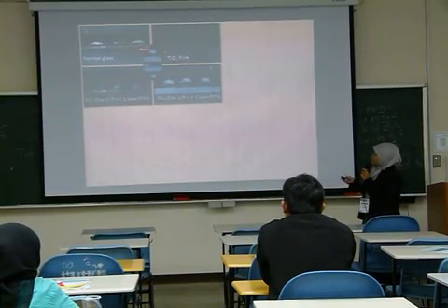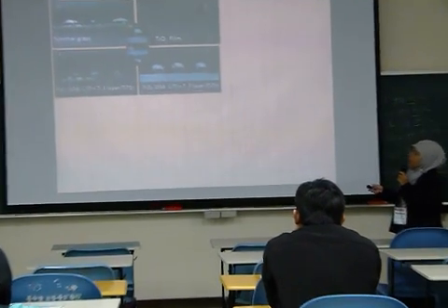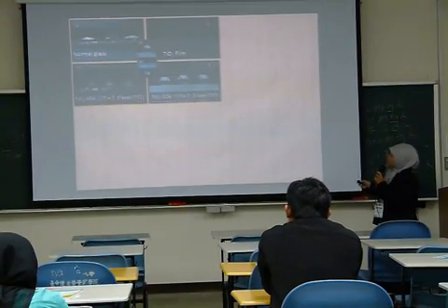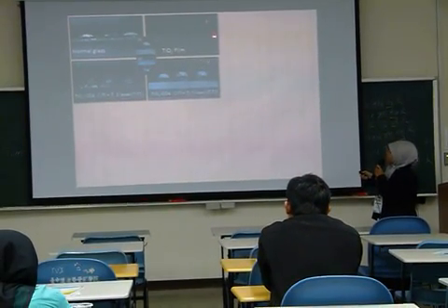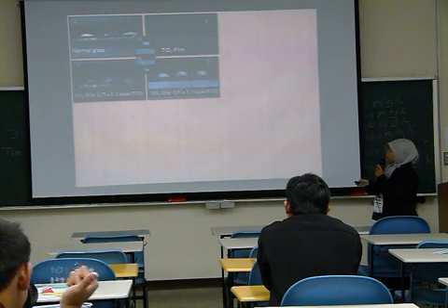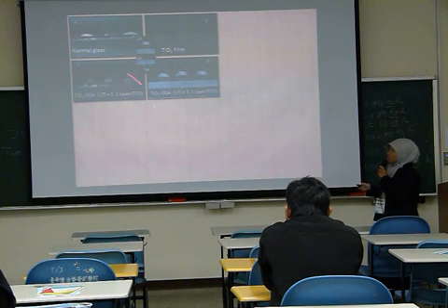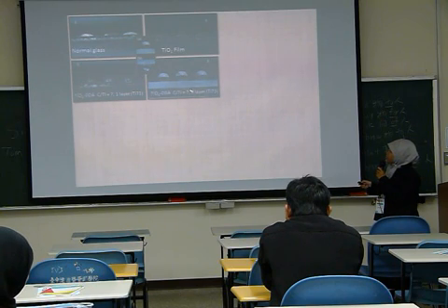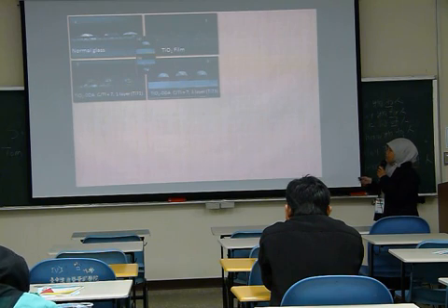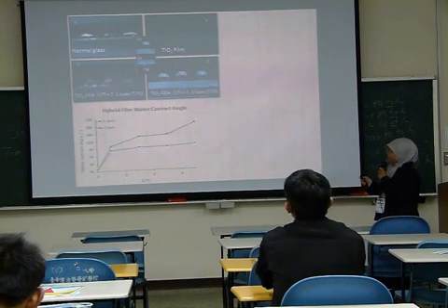Water droplets just spread on the glass, and if we apply the titanium dioxide film onto the glass, it's the same. It's more hydrophilic. But if we apply one layer of hybrid film, just one layer, it becomes more spherical, and after three layers, it becomes fully spherical. And quantitatively, we can see the contact angle from this data.